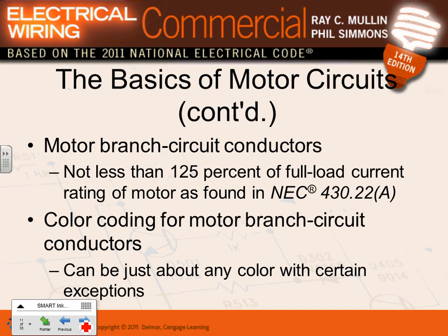Okay, I'm going to fly through these for one reason: we have done them, and we will do them again, guys. Basics of motor control. Motor branch circuits. Does that ring a bell, when we take 125% and multiply it by the full load current from the NEC code book? Everybody understand that one? We've done it multiple times.